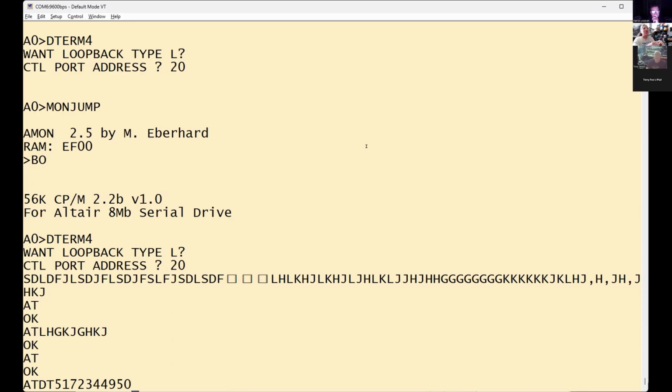If you could program one of those extra ROMs I sent and mail that to me, then I could try and read it in with the XG Pro and see what's different. Did you try programming it with a binary copy? I think I sent you a binary. Yeah, I tried the binary. It loads the same way. It looks exactly the same. Okay. So I'm thinking if I load in a known good ROM, then I should be able to see what's different.